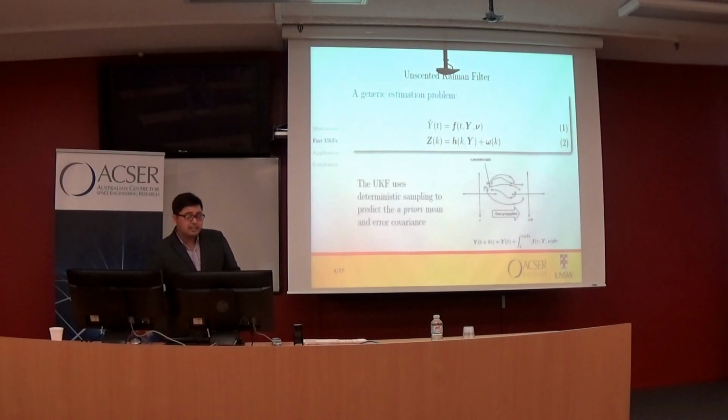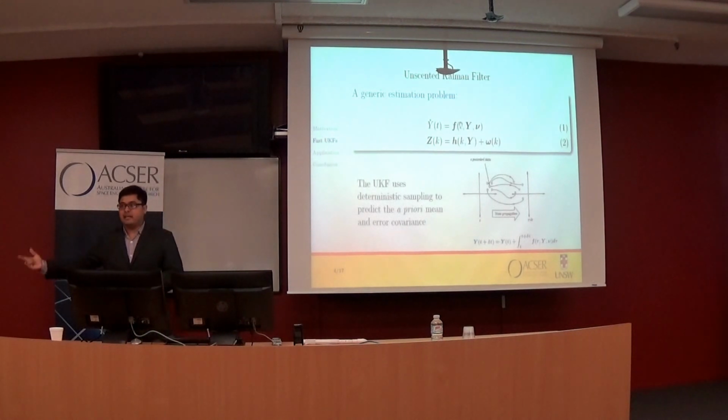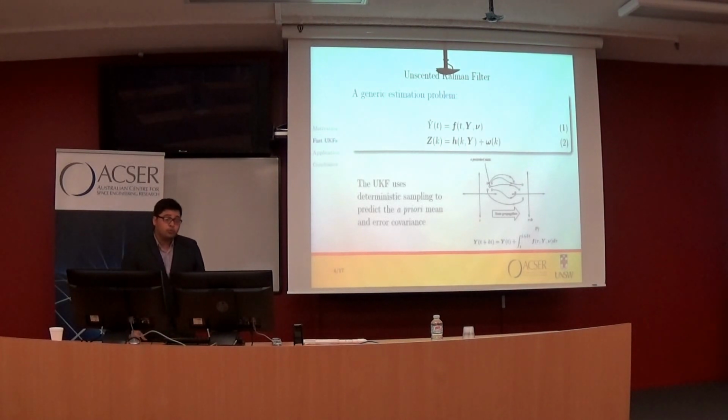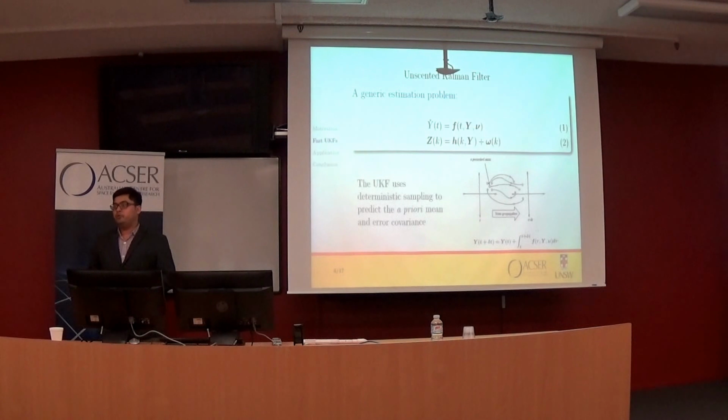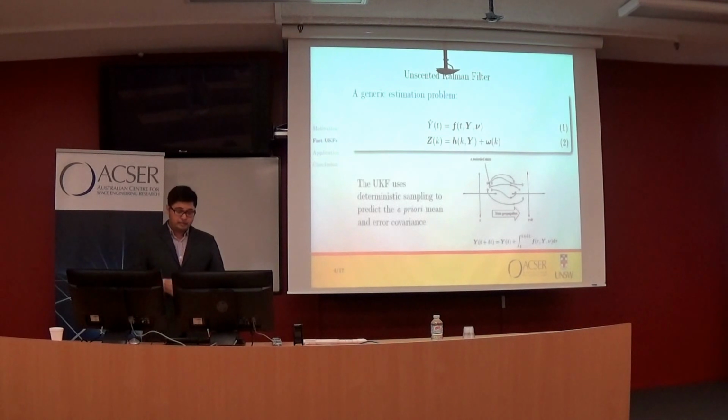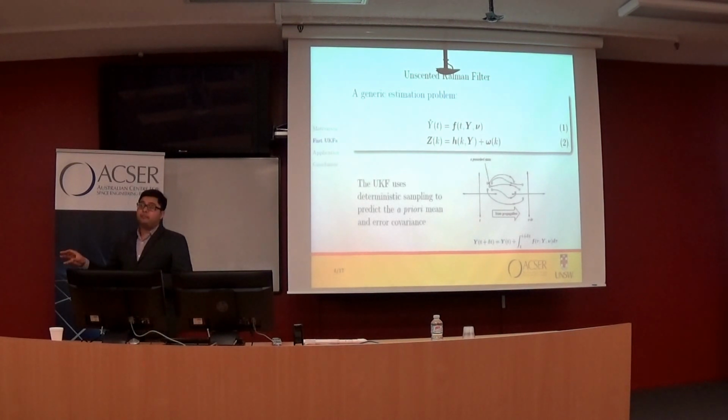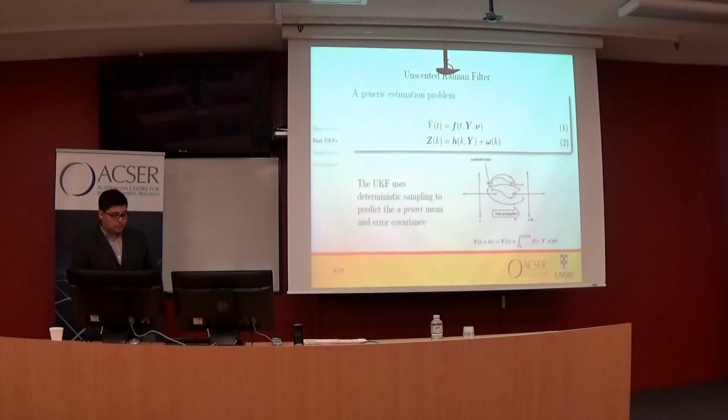In the normal extended Kalman filter, it takes the posterior state and uses this equation to propagate to the next time step by integration. We cannot use continuous time integration in a computer; it has to be done numerically. So for the EKF, it just takes this state and propagates it to the next step, and it assumes that this is our a priori mean at the next time, which is not exactly right. It is a good approximation for a mildly nonlinear system, but for a highly nonlinear system we have to do some rigorous approximation.